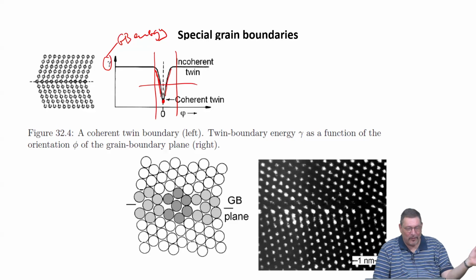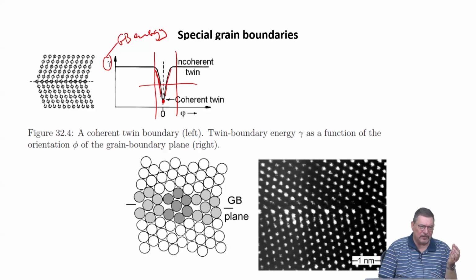And overall, maybe doing an analysis of the whole microstructure like you do in EBSD, and you press a button and you get number fraction of CSL boundaries will not give you a good answer. So maybe it's a good way to check some and see, because it would depend also on whether a twin boundary has been generated as a deformation-induced twin or whether it's a grown-in twin. The grown-in twins tend to have lower excess energy, so they are more like the coherent twin.